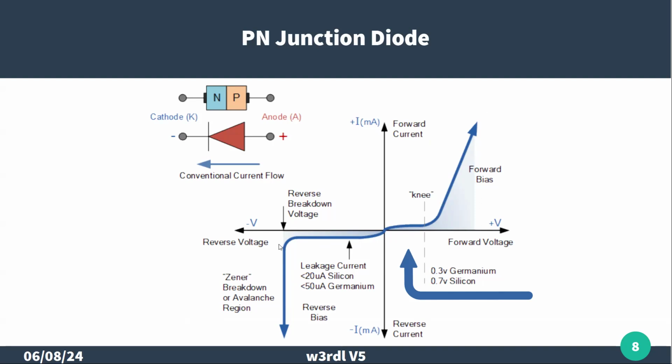And we use that effect to create what we call Zener diodes, where we actually use those in the reverse direction. And they can be manufactured so that that Zener effect is at specific voltages. So you can use it as a voltage reference. You can have it for 10 volts or 5 volts or whatever. And it makes a very good, stable voltage reference.